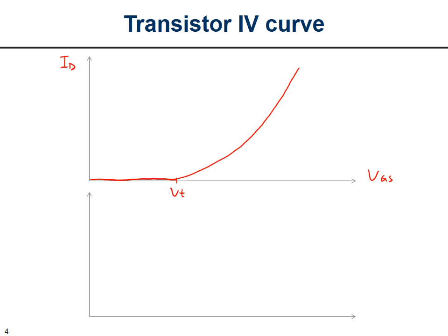Okay, now this is not the best picture when we want to talk about low power biomedical circuits, energy efficient computing elements, neuromorphic computing, etc. Because the assumption that current is zero below the threshold voltage works fine for digital circuits. It turns out it's not very appropriate for low power analog circuits, or for that matter, low power digital circuits.